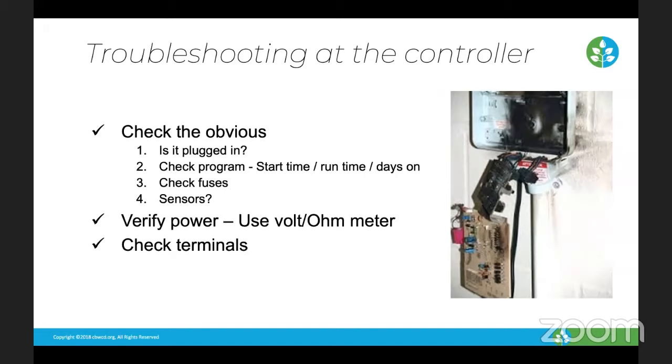And the reason why you might not notice that there's no AC power, that you can't tell that there's any power going into the controller, is because they have a backup battery, and that backup battery keeps the time and the date, so the screen is still going to look the same. However, the battery is not going to be able to operate the irrigation control valves.